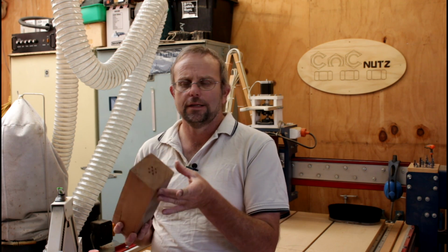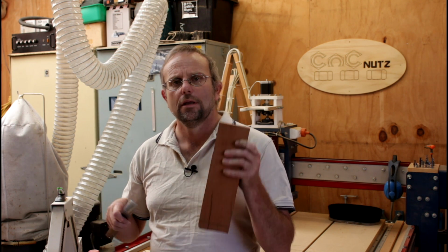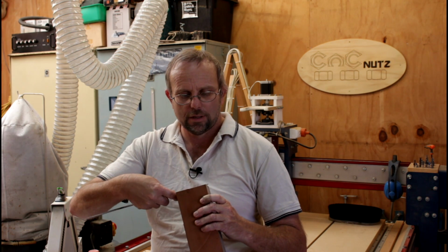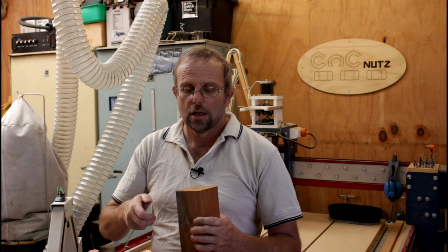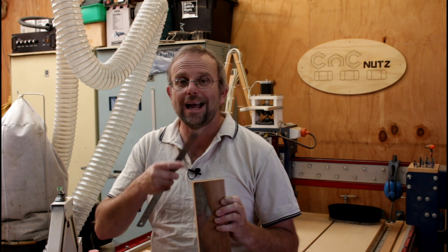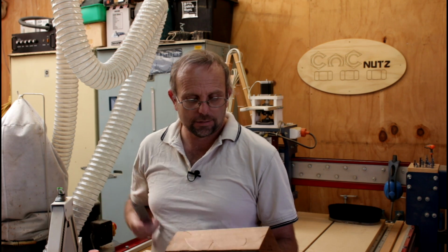I originally cut it out as a square, and then from the square I took 3 measurements. I measured across the flats 75 millimeters, across the diagonal 107 millimeters, and its overall length 270 millimeters. From these 3 measurements I then create the file to turn that into a cylinder. It's important I do this first, that way I know how big the material can be before I create the file to make the actual mallet shape.